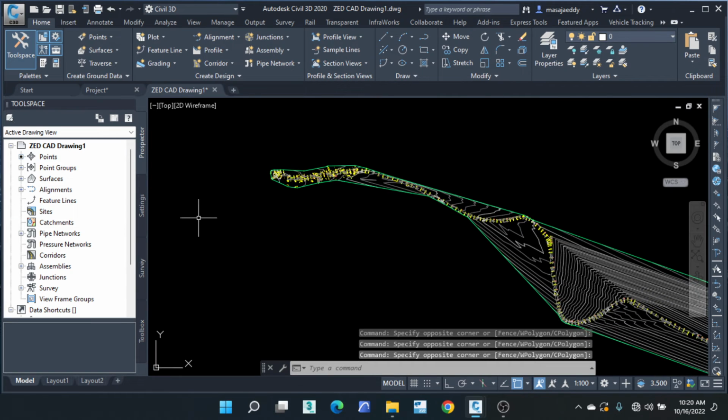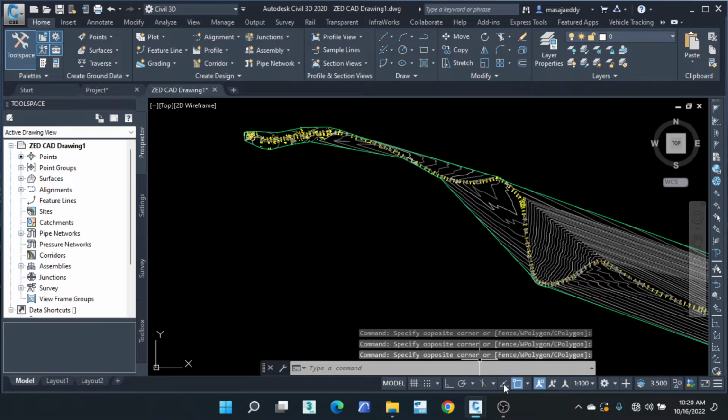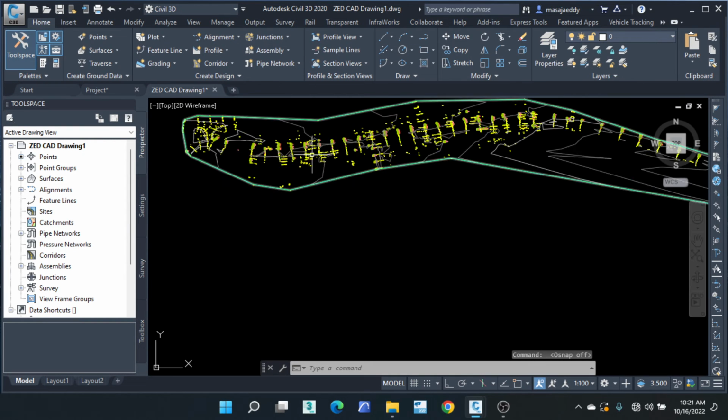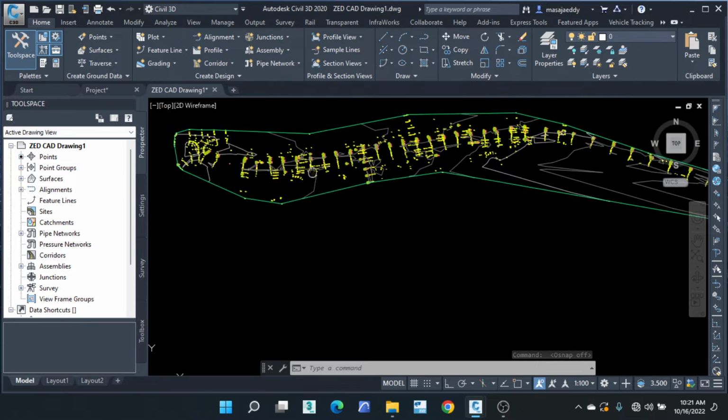So in most cases, what causes some of these lags is that when you have this snapping tool on and you go to an area that has multiple points, it tends to snap to all the points, so that makes the computer calculate too many commands at the same time, and that's making the lag. So what I usually do is turn off this snapping cursor rule. It's far much easier while you're doing the navigation within the software.